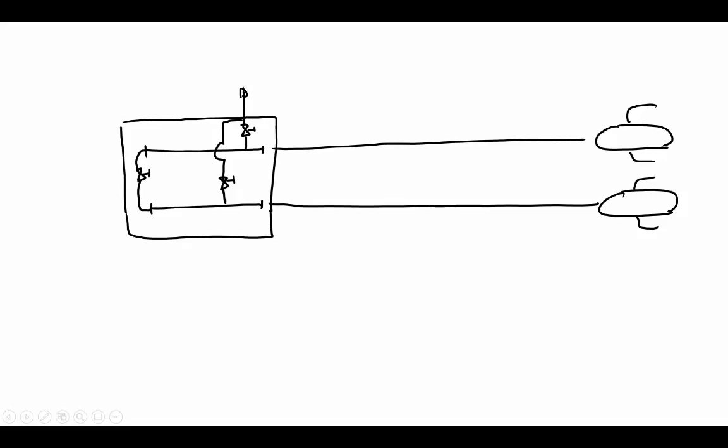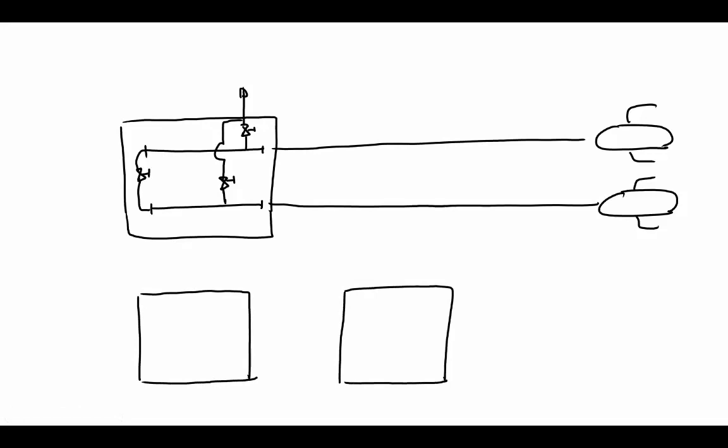You can also have the same configuration if you have, for example, several templates. If pigging is an issue in your field, you have to make frequent pigging. Then you have two templates. You have your wells here, or they can go to this manifold. Also the same thing here. Remember, the well is a part of the template.